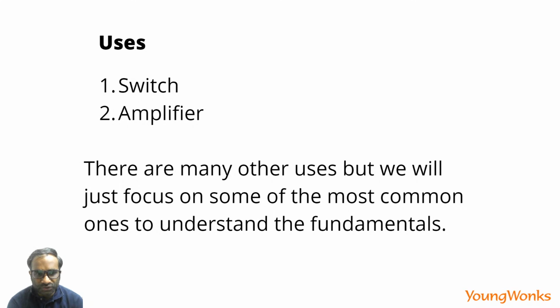That makes it very useful because that allows us, whenever we write programs, let's say on a Raspberry Pi, for it to actually turn on an LED. This is what's happening: we're writing code which turns on transistors, but it allows it to actually work with higher current and higher voltage than the GPIOs.